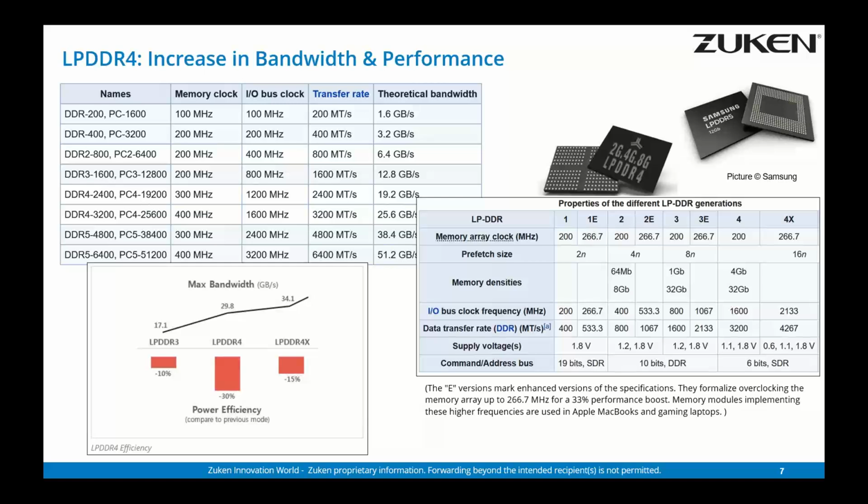And if we look onto the low power breeds depicted on the right-hand table, we see that if we look on low power DDR4, the performance, and even further if we look on low power DDR4X, which is the voltage scale down version, that's pretty close to the most sophisticated memories which are on the market these days, close to DDR5. So with a gain in the power efficiency, we have an incredible amount of bandwidth and memory performance.